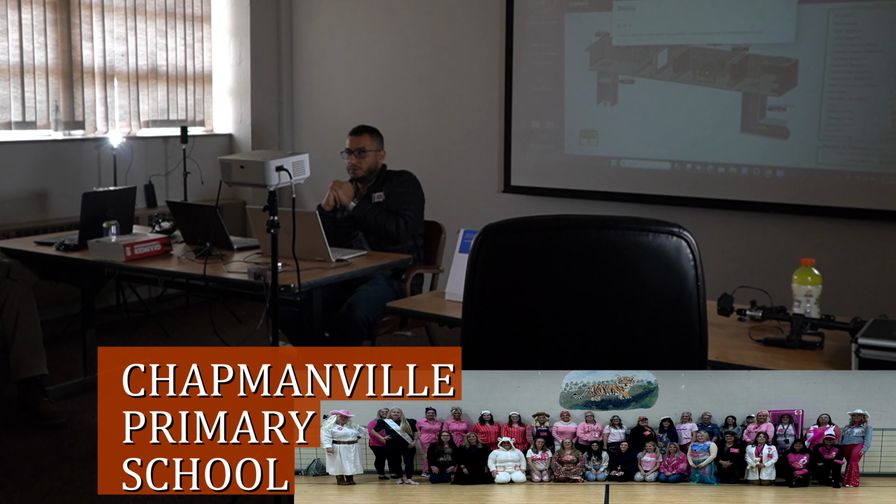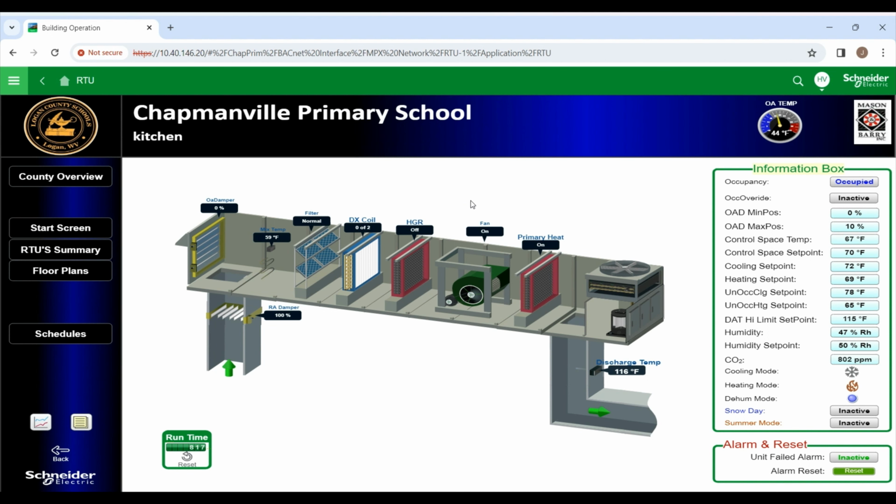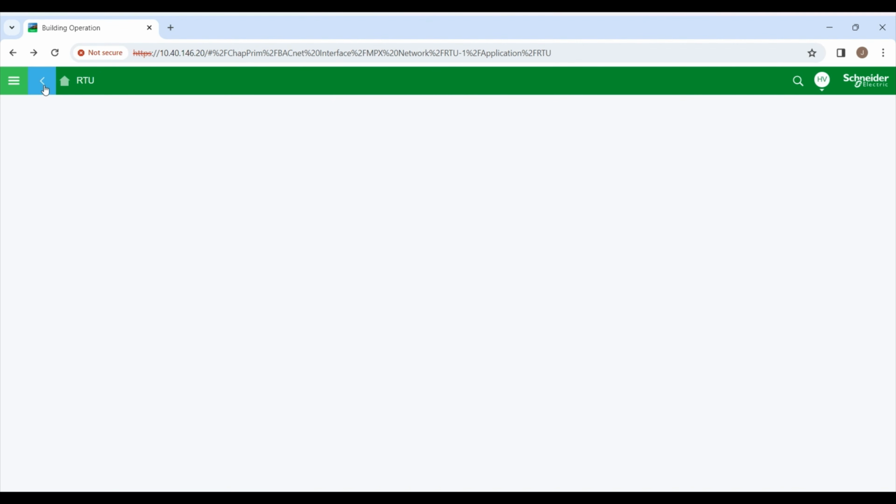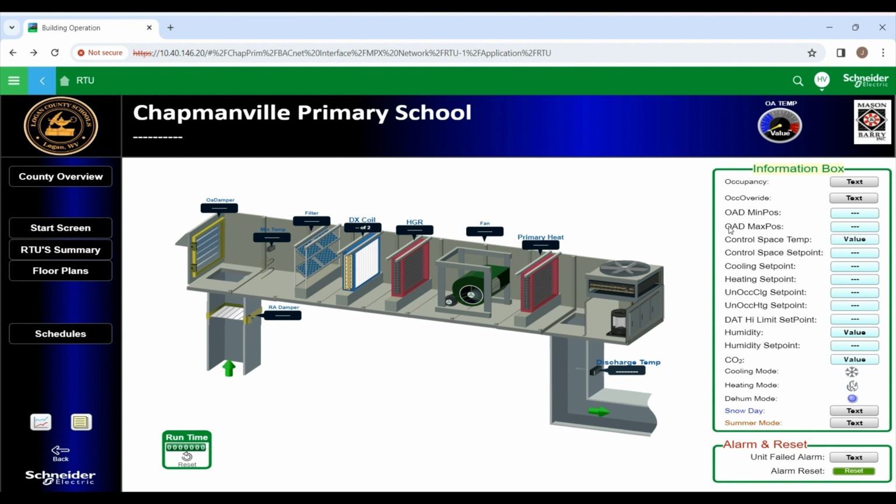So what I was getting at is if we go back to the testing part, if we want to test the heat, and it's already 75 in there, we can't raise active set point up to 78 to watch it kick on because it's limited to 75 max. What you can do, which is a little trick, but I would say it's a dangerous one, you can force the space temperature itself for an hour. But I was skeptical about that because a lot of guys will do that and forget about it, and it will be big trouble.